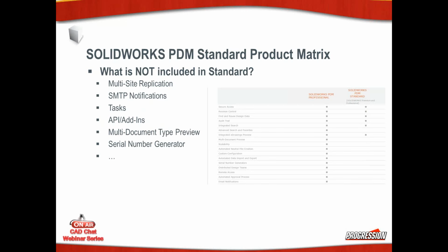What is not included? Important to perhaps outline again when we're talking about the differences between Professional and Standard PDM. Multi-site replication is not included with PDM Standard. And again, this is aligned much with the Workgroup product. That product does not have any multi-site replication either. With Standard, there will be no SMTP notifications available. So you won't be able to send emails essentially to clients as, say, you submit for release or submit for approvals, things like this. But there is internal, shall we say, database notifications. So when the client logs into their Vault view, they will get the notifications that way.